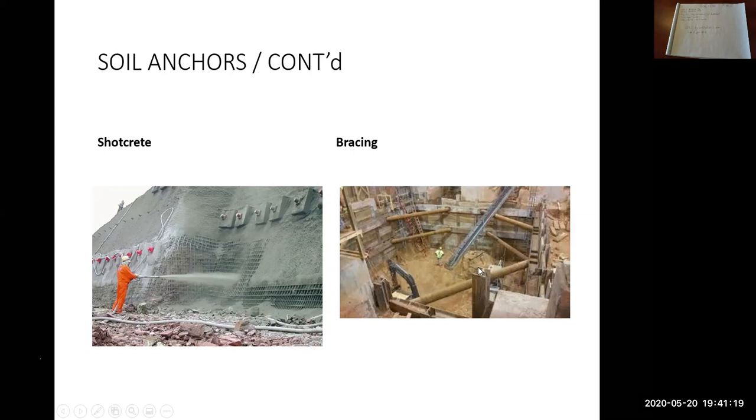It looks literally like the letter H or I with some height to it. These are pounded into the ground vertically at some spacing. In between each one, timber lagging is slid down the slot in the H. So that's what this shoring system is, a timber lagging H pile type system.